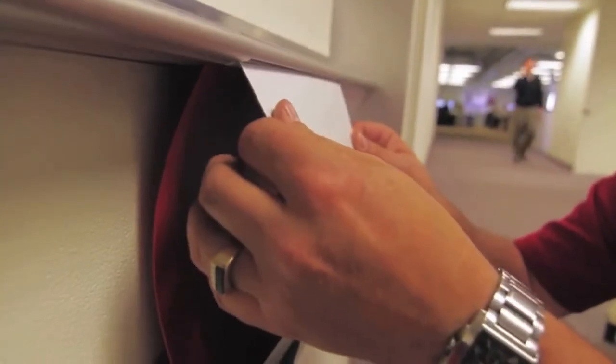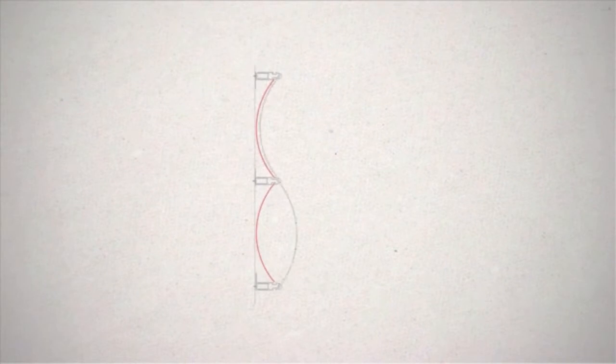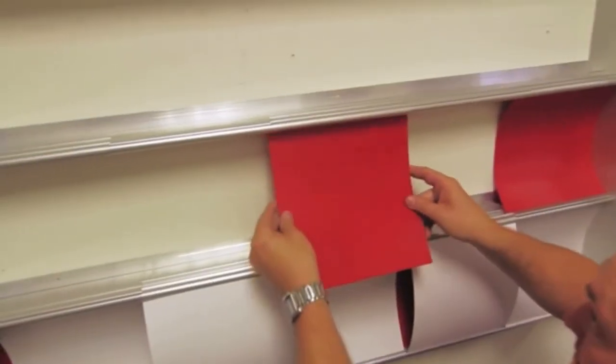Your shadow tiles should always meet behind the concave ripple tile in order to hide the join. Be sure to place the shadow tiles in the channel shown and not the groove for the ripple tiles. When placed correctly, ripple tiles alternate in curvature, with a convex tile always followed by a concave in both directions.